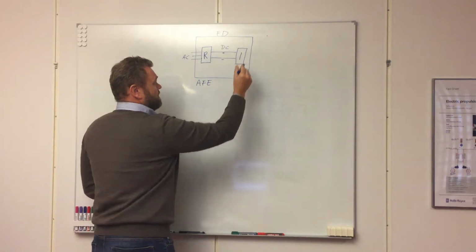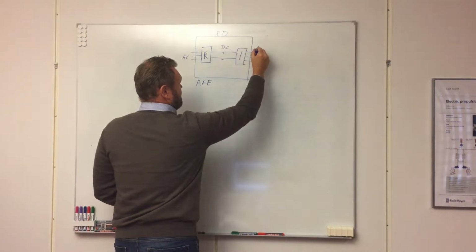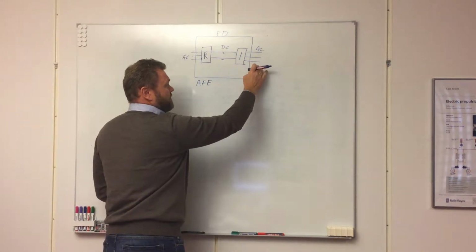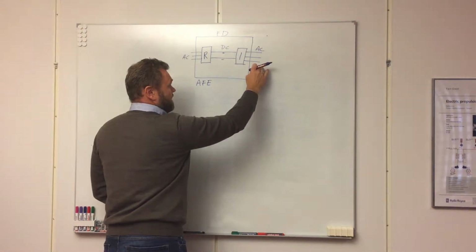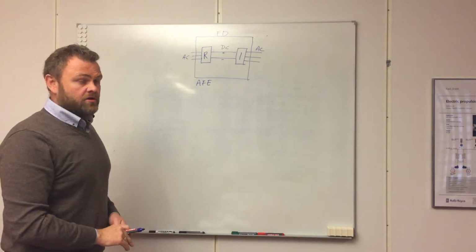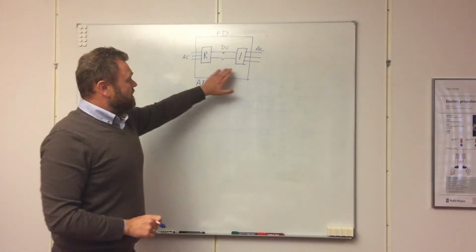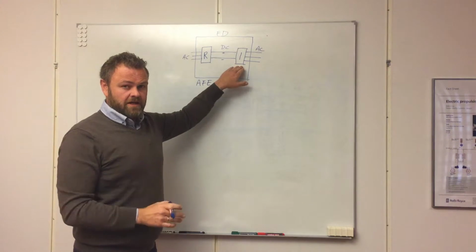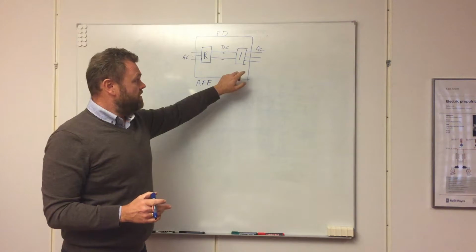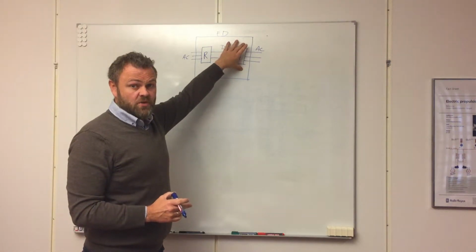The inverter is then making AC again, and at whatever frequency you would like it to be, dependent on which type of equipment you are controlling. So rectifier and inverter. You will in fact hear that some people say frequency converter about these internal units as well.